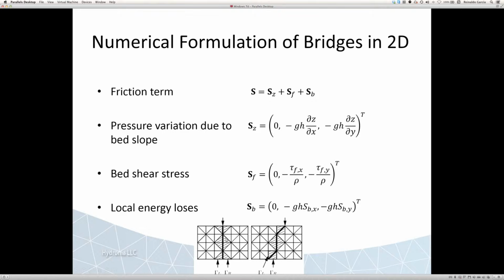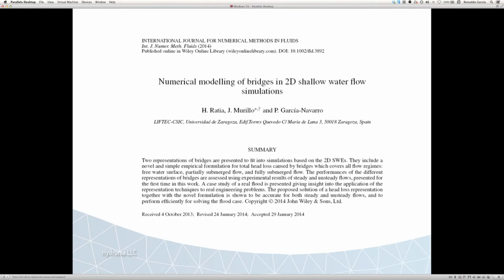So you get a local calculation, and the local calculation is based on the local geometry of the breach. So if it happens that these two elements fall in for pressure flow, maybe you have a pier here or any other form of structure, that geometry will be computed and used for the calculations locally between the two cells across the breach. So it's a very detailed calculation that goes on when you implement a breach in RiverFlow2D.